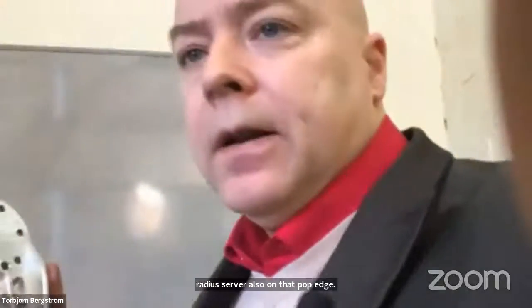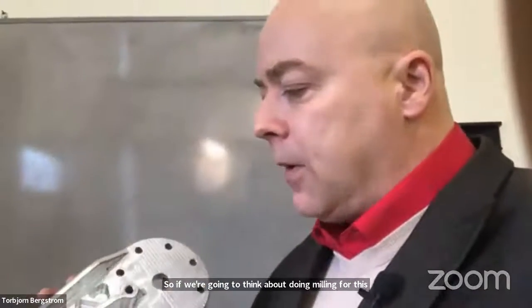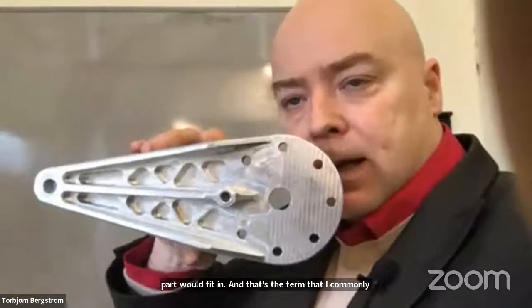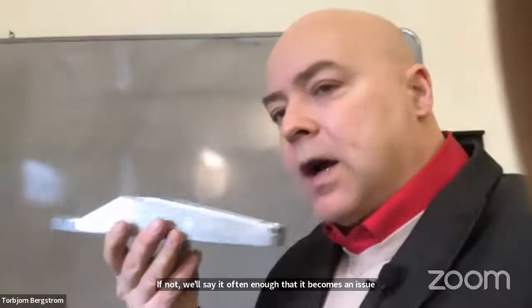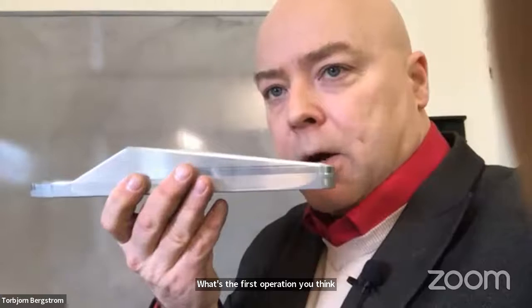So if we're going to think about doing milling for this part, let's assume our stock material is a shoebox that this part would fit in. And that's a term that I commonly use. I've heard other people use it too, so it may be an industry standard term. If not, we'll say it often enough that it becomes an industry standard term. So if the stock is the shoebox that this part fits in, what's the first operation you think we want to do as we make this part?